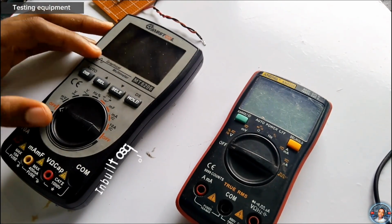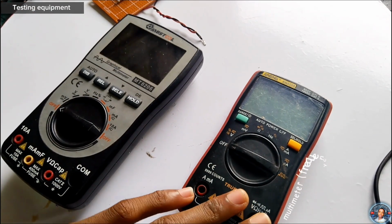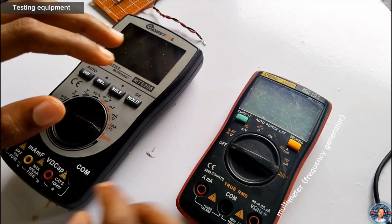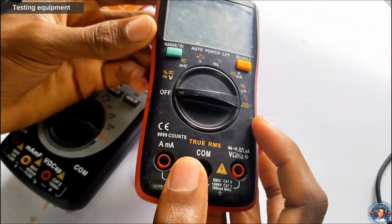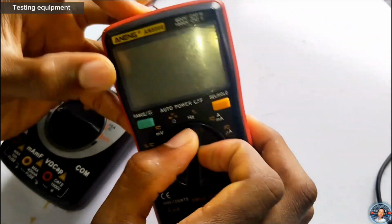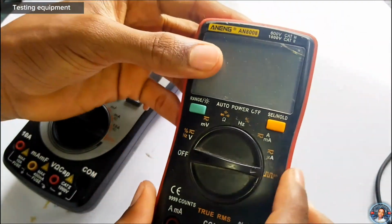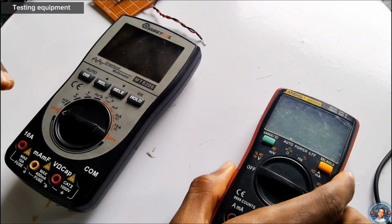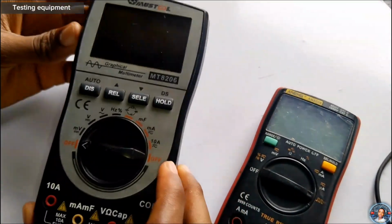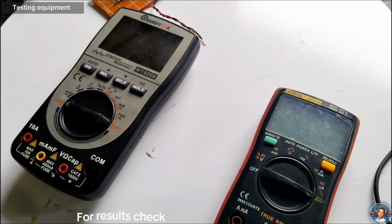Now I have two meters right here. This is the oscilloscope meter, and you can also use it to measure voltage and current, and this other meter is a voltage and current multimeter. This meter I'm going to use to create the frequency, the square wave. I'm going to turn this to the square wave side, so that it produces a 50 Hz, 50% duty cycle square wave for me. The battery is not yet in. And this meter I'm going to use to measure the output wave, so you can see the amplification yourself. Without wasting much time, let's go to the connection process right away.